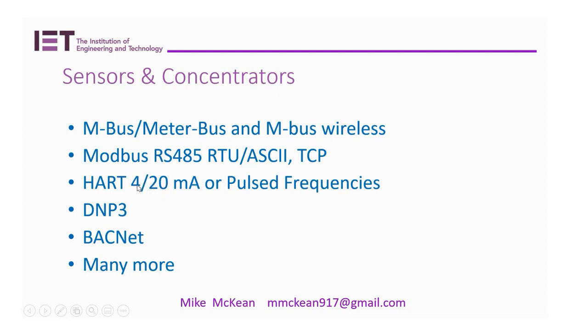which means it's a minimal reading. HART is often used in oil and gas environments, in oil fields, etc. So 4 milliamps might be a reading for a gas tank saying that it's a small amount of gas in that tank. 20 milliamps, for instance, might mean it's full, and it's graduated, calibrated in between at the gateway end to say, okay, it's 20 milliamps, the tank's full, for instance. And that works over a pair of wires.